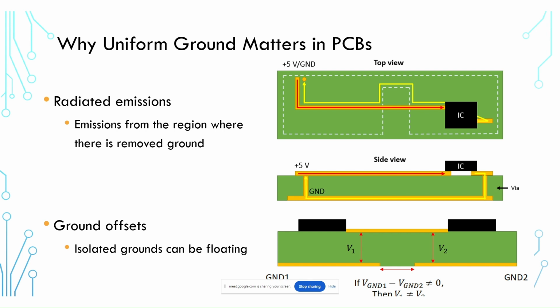And it is that differential output that allows you to route those two wires around, let's say plug them into a PCB, and then be able to get that signal into a differential interface like an ADC, or for example, a differential amplifier, and then read what the signal is coming off of that sensor. So the same principle applies in high-speed differential pairs, but we use differential pairs with high-speed signals for a different reason. And so I think that's something we could get into maybe in a future presentation where we talk more about high speed.